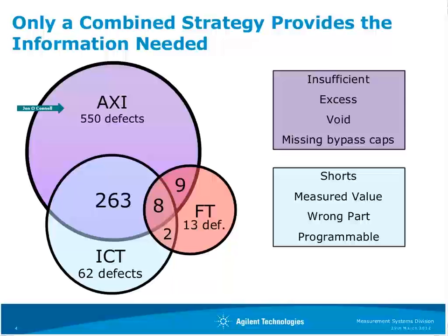In complementary tests, a contribution from technology like AXI and AOI means that the operator can very quickly review the PCB assembly images at different surface mount stages. This equipment uses known good joint algorithms and presents any failure or marginal cases to the operator to review.